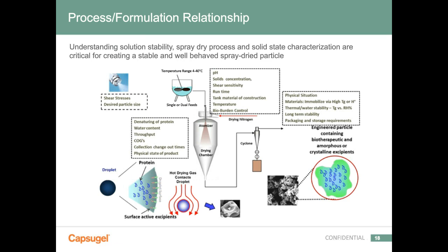So lastly, the collection itself by the cyclone is also critical. In this case, it really comes into account what the overall product yield is. So by having the right initial input and drying kinetics, and then having a high efficiency cyclone that's able to separate the dense particles from the inert gas, we can have a nice high product yield, which is typically greater than 90%.